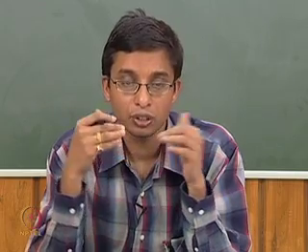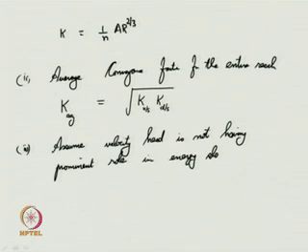So, this is just an initial approximation. We are suggesting that velocity head, initially we are assuming, is not having a prominent role in the computation of energy head, or rather, a better terminology, not having a prominent role in energy slope. This is the initial assumption.